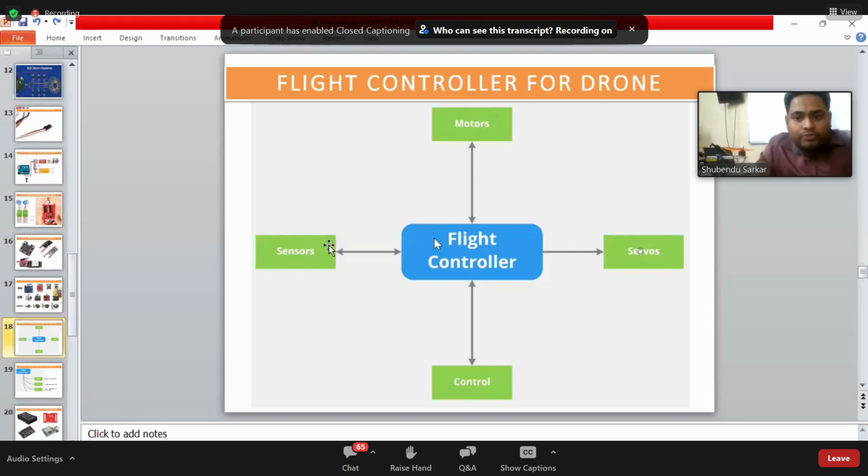Similarly, there are some magnetic sensors and there is some kind of GPS over there. So lots of things inside it. But in most cases, we put the GPS externally. And there are servos also involved. If we are making an airplane or a bicopter, remember, airplane means fixed wing drones, and a bicopter involves servos also, because we are going to change the direction of the motor or we are going to change the rudder.